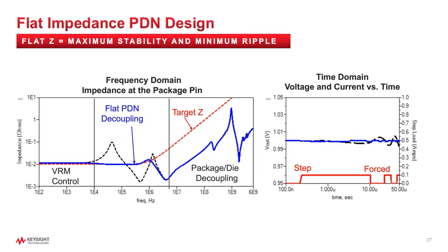Eventually, enough capacitors can be added to drive the impedance below the target impedance. However, there is a better way that can maximize performance and minimize cost at the same time. Instead of just leveraging a suggested capacitor value, what if we use the simple L over target Z squared equation to get the C required for flat impedance?